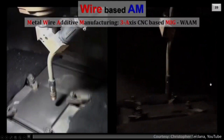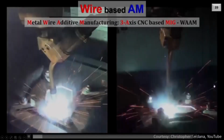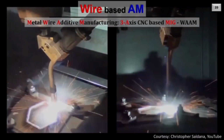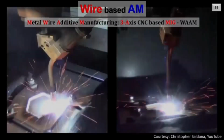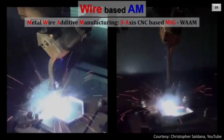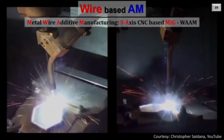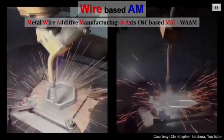So this is a video of an example of 3-axis CNC based MIG welding WAAM. In this case, you can see the MIG welding gun is mounted on the spindle head of a 3-axis CNC machine, and it is depositing the material on a substrate. The gun cannot tilt in this case. It can be noticed that there is no possibility of realizing overhanging features. Of course, a very small amount of overhang can be obtained because some amount of material can be sustained due to the surface tension of the deposited material. However, large overhangs, which will require a support mechanism, are not possible to build on 3-axis CNC machines.